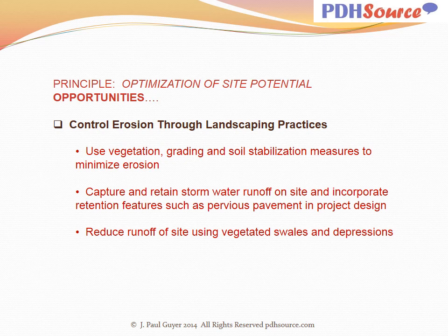There's kind of an underlying thought here, and that is that whatever comes onto your site naturally, you should try to leave it on your site. And so that means the soil that's there on your site, keep it there. Or water that falls on your site in the form of rain, generally speaking, keep that water on your site so that it percolates into the groundwater or drains into an existing drainage channel or creek or something like that.